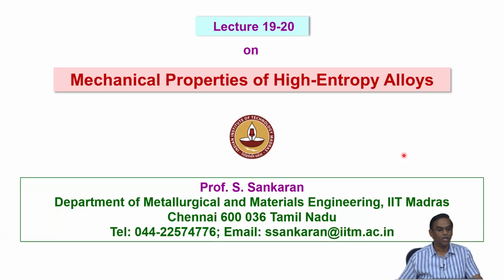This clearly tells us that dislocations exist in the as-cast condition. That means they can be manipulated. The stacking fault energy generally comes down. This is what the literature says, but of course there are exceptions, though mostly the stacking fault energy comes down.